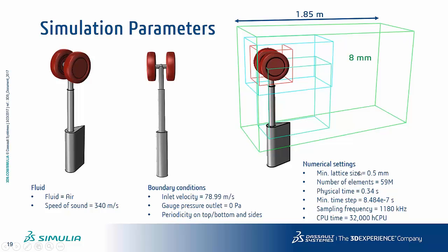So with that we actually have a refinement that is progressively, let's say, unrefining. We've got a finer resolution near the geometry so that we can capture the smallest fluctuations and the smallest gradients of fluid, and then we progressively unrefine so that the computation cost becomes accessible, and so that we don't have too strong a transition of lattice between the geometry and the far field, so that you can capture the wake conveniently.